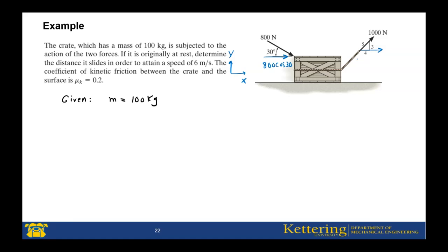What is the component of the 1000 Newton force along x? It would be 1000 cosine of alpha. That's cosine of alpha, which will be 36.87 degrees. And how much is the final product? That's 800. Correct. This one is 800. Why?